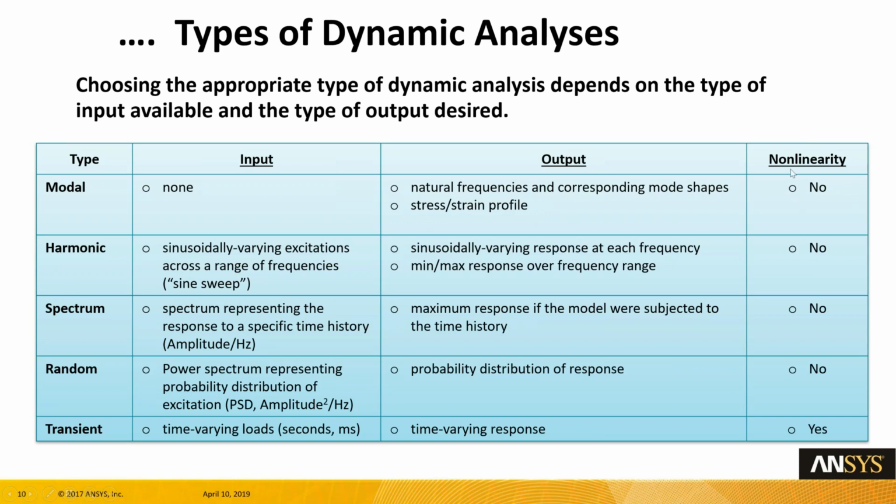Any nonlinearity involved? Like we said, no, there's no nonlinearity allowed in modal analysis. This is not an ANSYS limitation, by the way. This is just finite element methods in action, just the formulation. Any program out there that does FEA modal analysis has no nonlinearity involved, because we will show you the formula, the differential equations that are being solved. It just doesn't allow any nonlinearity.